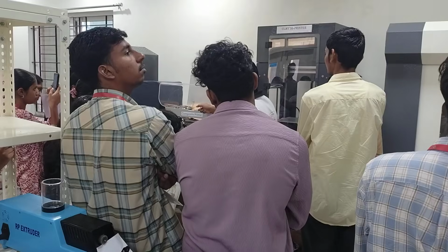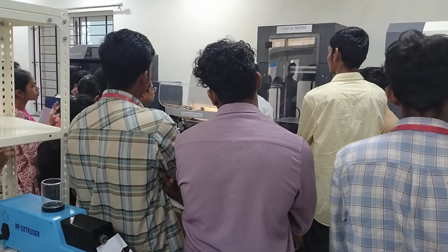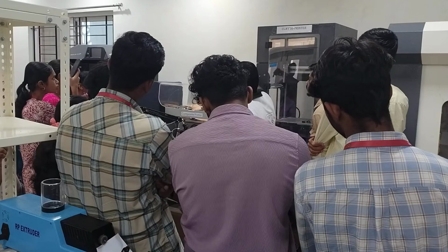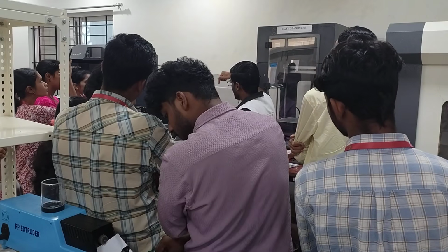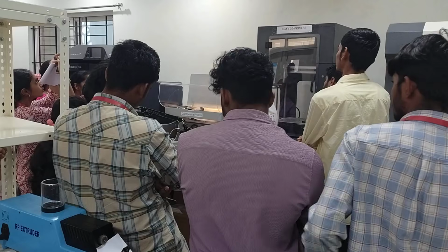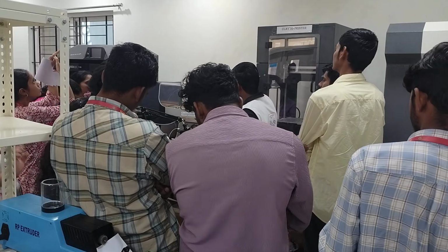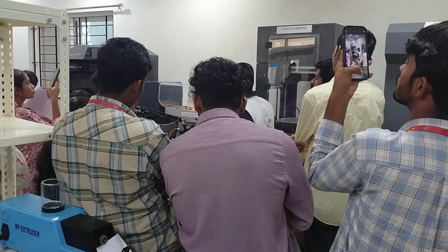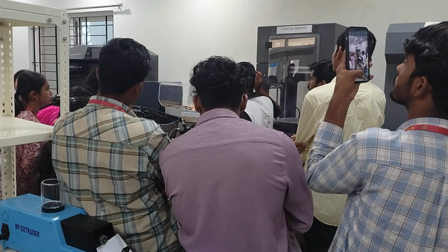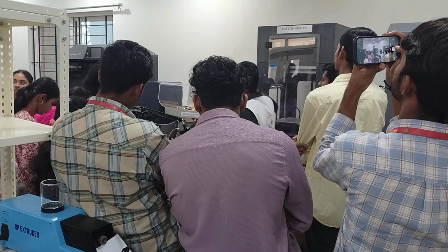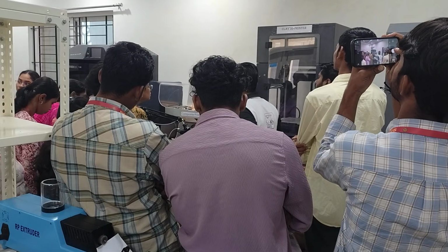So at the end, it prints something extra. You can say that's a wastage of material, but every layer it goes and calibrates. The sensor calibrates whether the printed part is at the same level as intended or not. So a kind of well will be printed at the corner and our main part will be printed here. I have made a small mistake, that I have not placed the glue on it. I'll see whether the print is coming good. If it is not coming good, I'll have to put the glue on it.